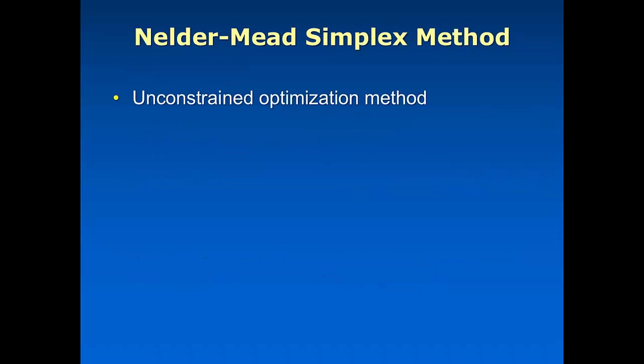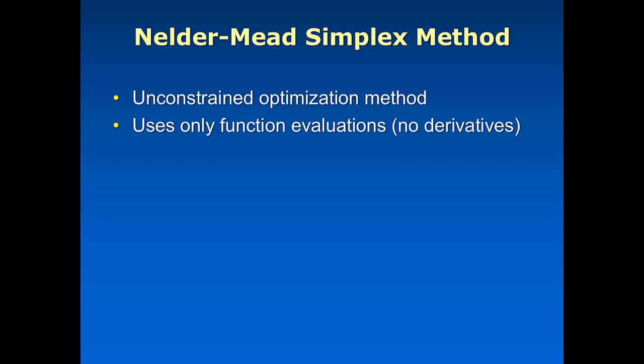Now, the simplex method is a fairly well-known optimization method, and we use it in the wastewater industry because it is something that allows us to do the optimization through evaluating successive versions of the model under different inputs. It doesn't require us to do any sort of analytical analysis of the derivatives or anything.